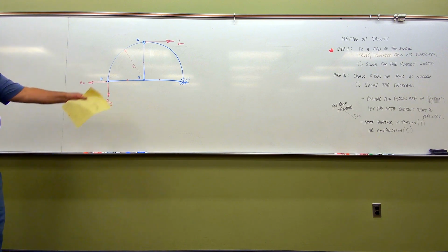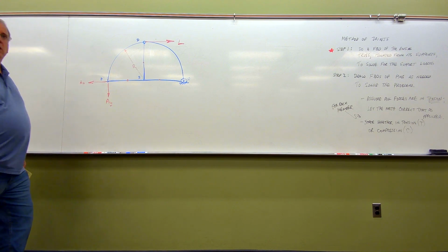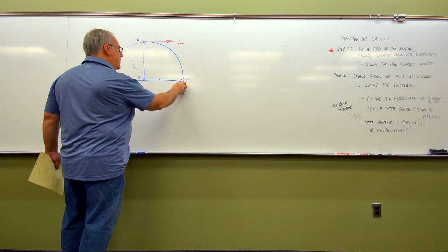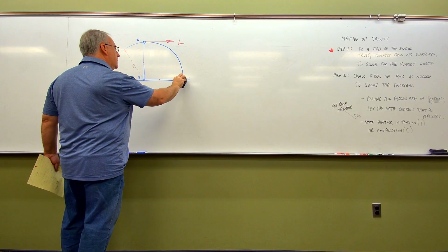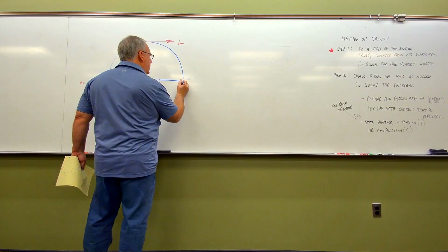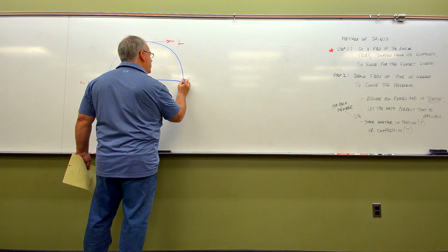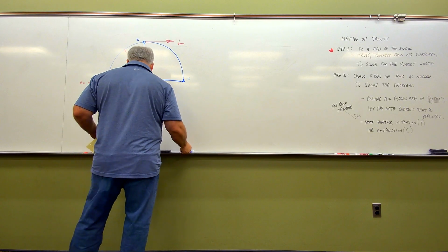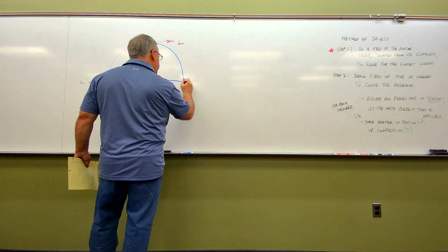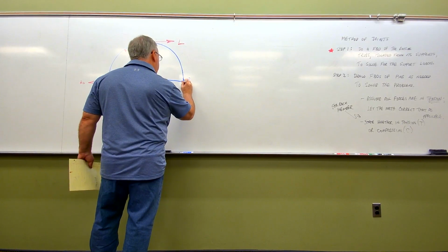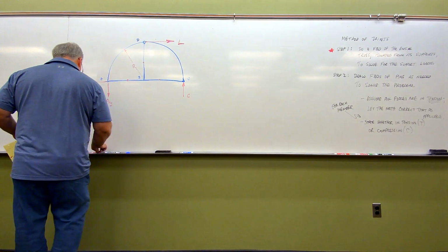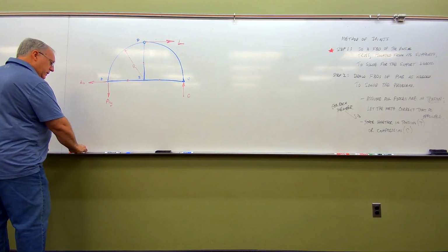Over here, for the roller at C, we know there's going to be a single force here, and it's going to be normal to this plane. So I'll get rid of this. Bring this together like so. And in this case here, I'm going to go ahead and assume that this force is drawn upward. And we'll call this one C, since that's just what that roller was known as.